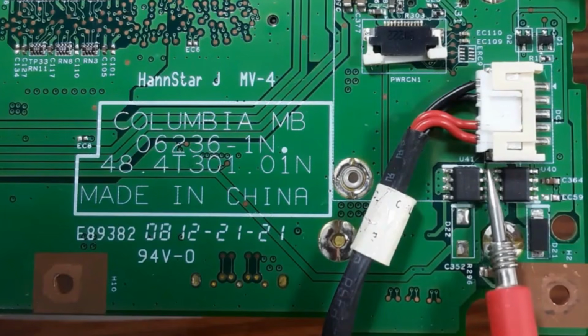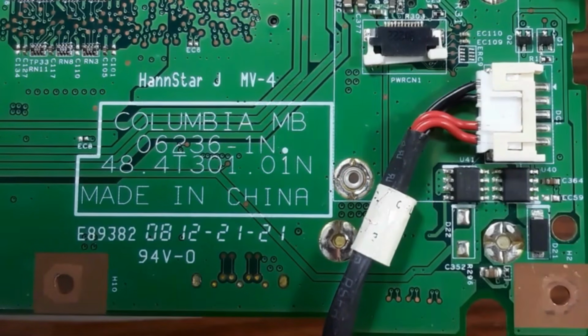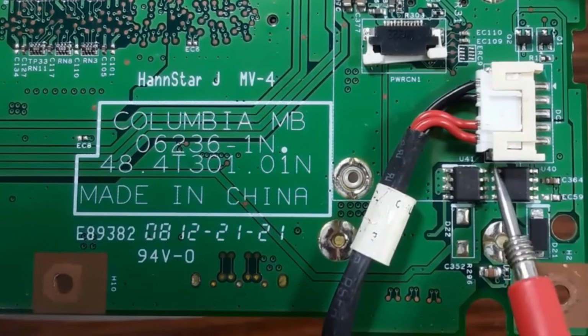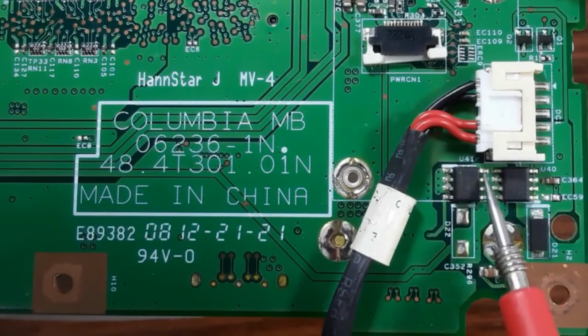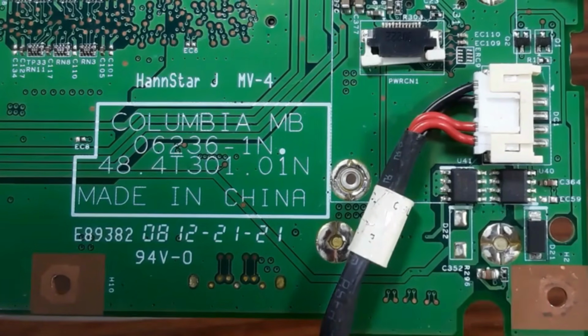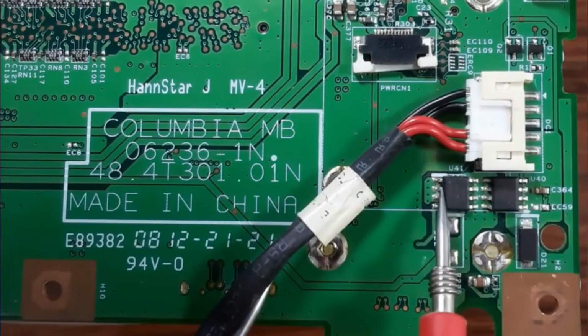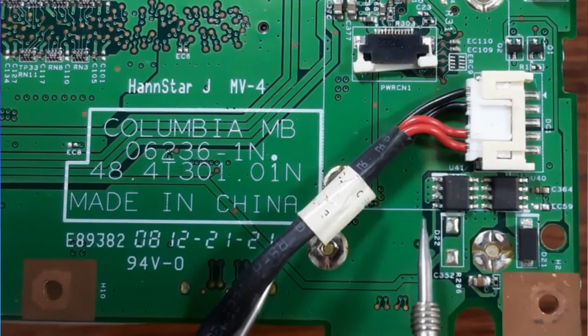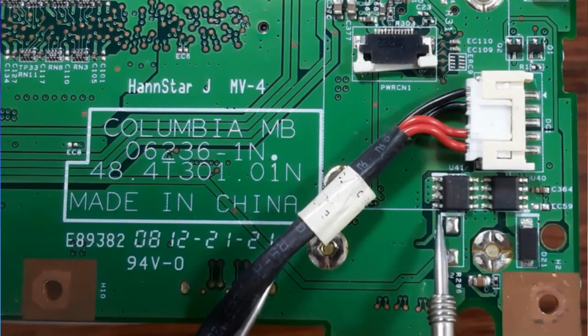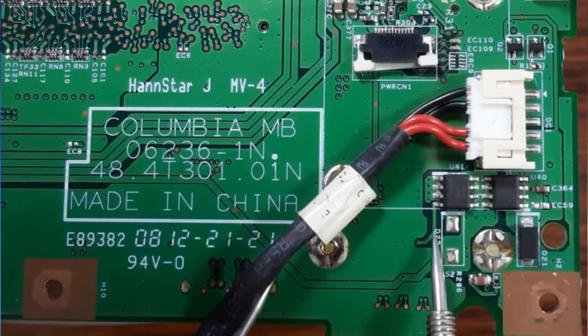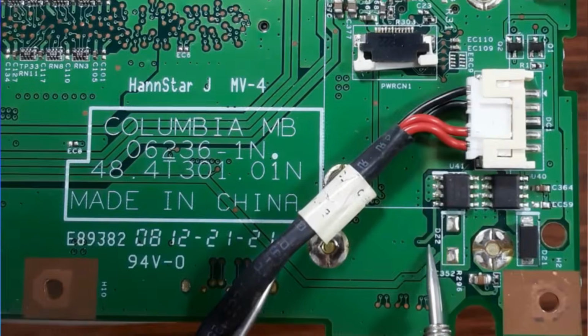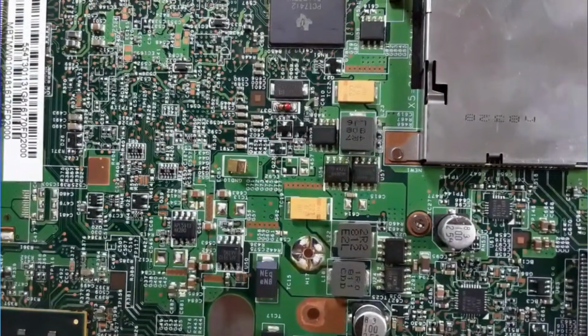And also all these 4 pins are connected to this. Why? As we see, because here we have the same color, the green color. All these 4 pins and these 4 pins are connected to this green color, meaning this is the same path. But for example, for this MOSFET, as you can see, we have here 3 terminals connected together with the same color, but this one, no, this one is connected to this bus, meaning this is the gate.